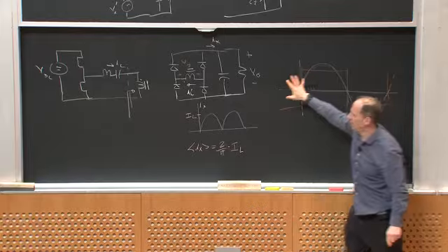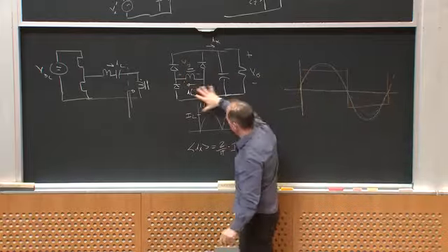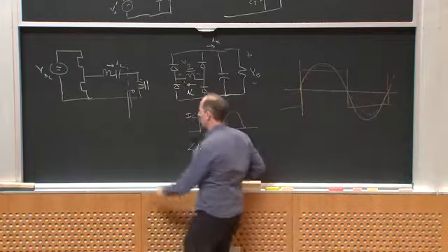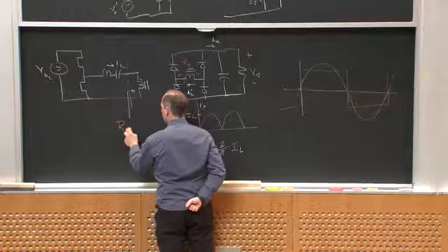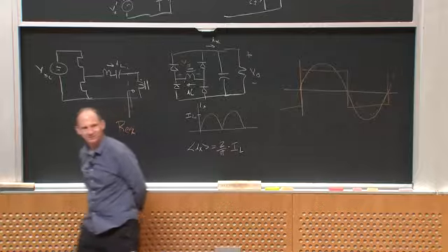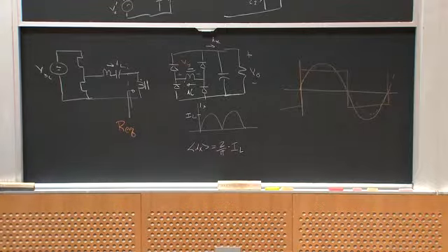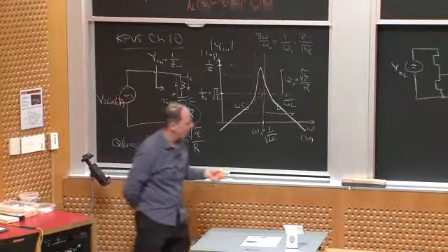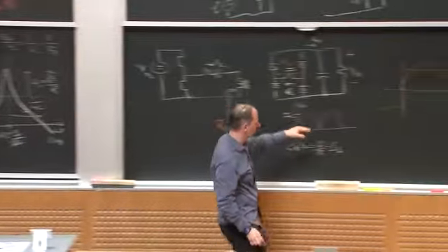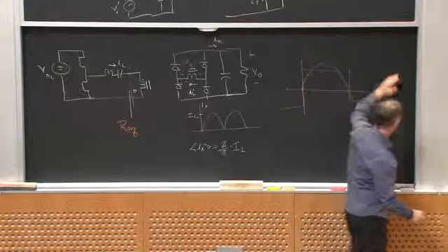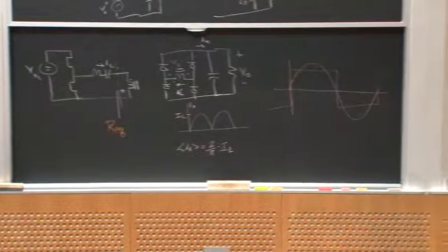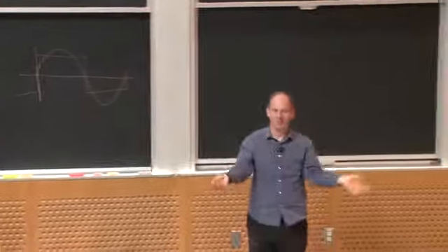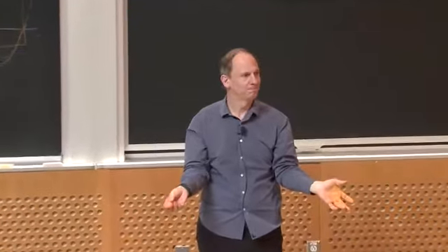So essentially, this whole rectifier network reflected through this transformer looks like an equivalent resistance. And I'm back exactly to this original model I had. The only thing I've done is I've said, I don't care about the harmonics because as long as the current's close to sinusoidal, almost all the power is in the fundamental.